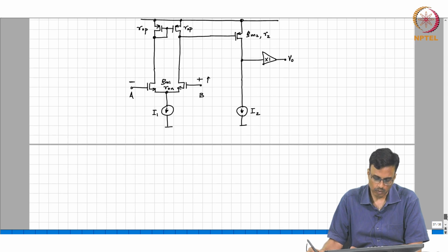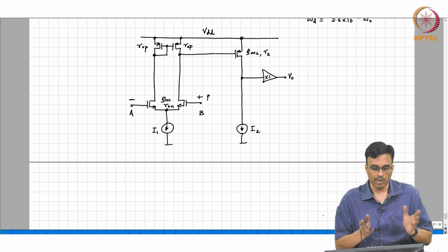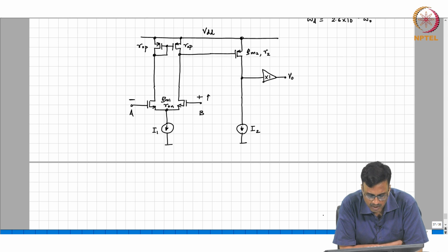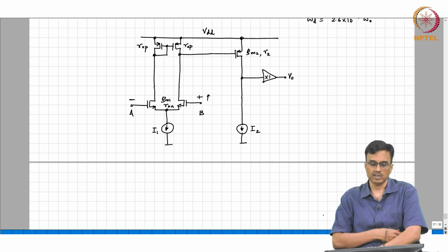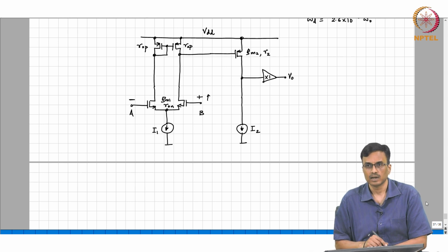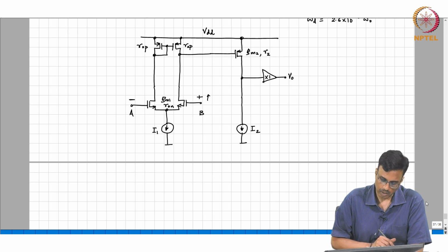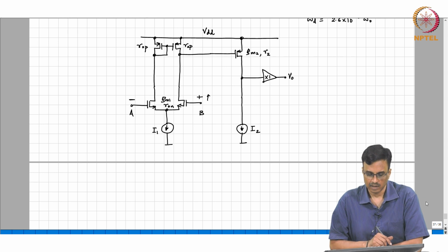All right. So, now remember that you can never operate an op amp in open loop, it is part of some negative feedback loop, and therefore, the potentials at A and B will be the same, and consequently all transistors are operating in saturation, everybody is happy. So, now the question is, what do you call the small signal equivalent, as far as small signal operation is concerned.